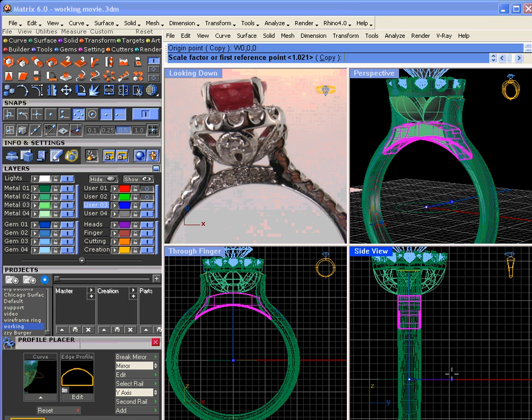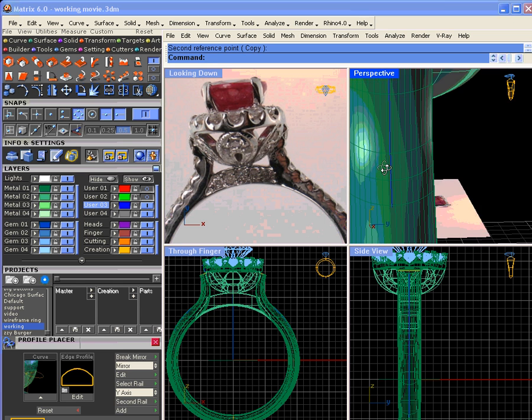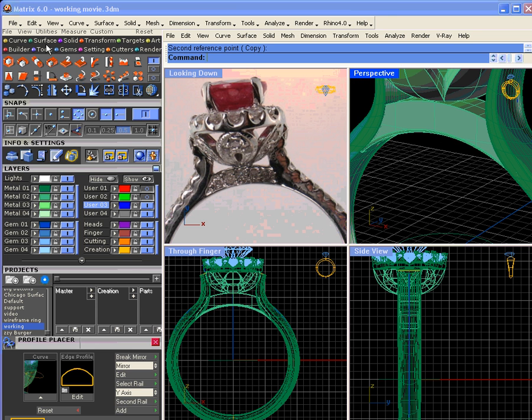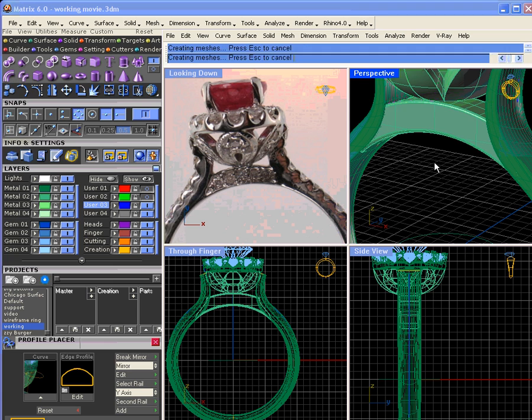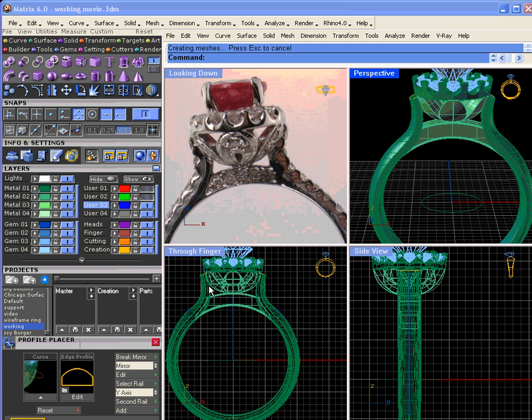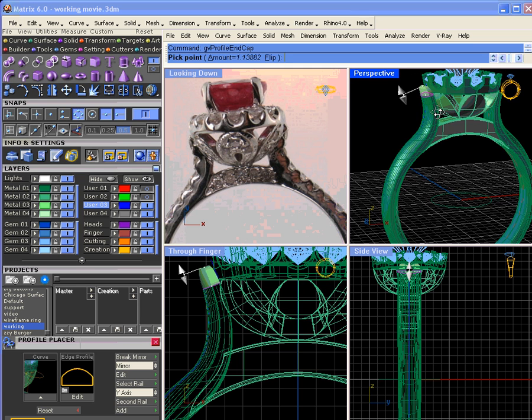F4. So we'll 1D scale this piece in again, so it's inside. There we go. And while I'm at it, I'm going to go ahead and fillet, solid fillet, 0.125, and we'll do this edge and this edge. There we go. And we'll do profile cap again.